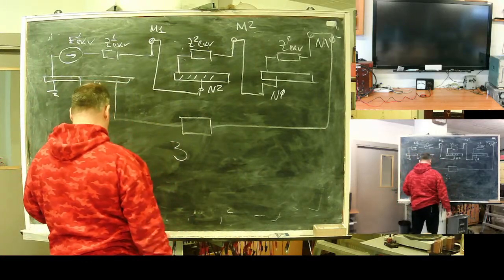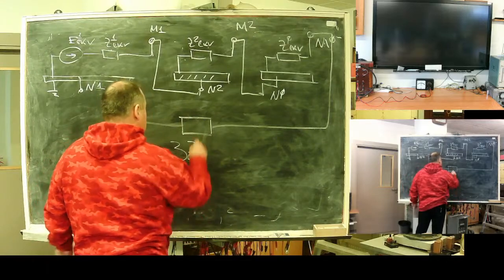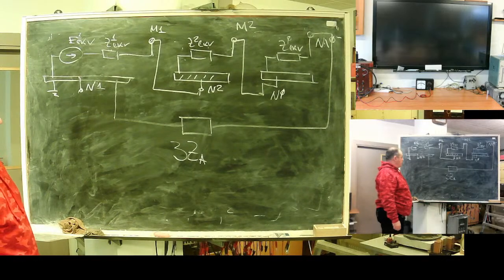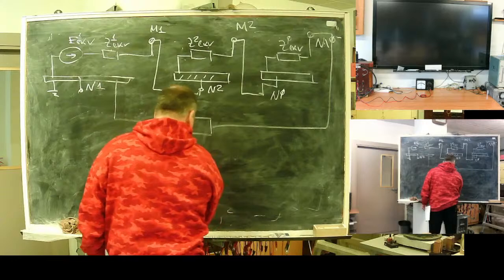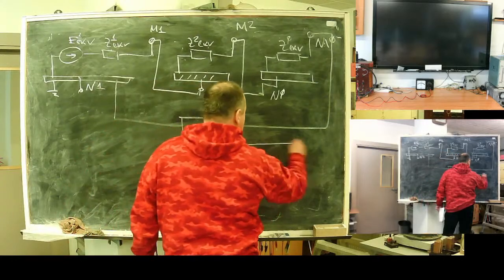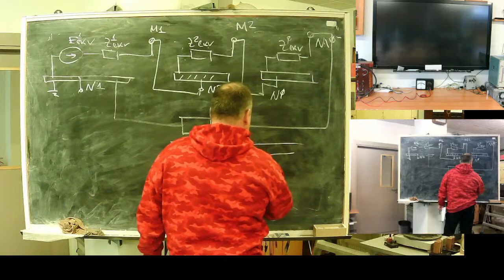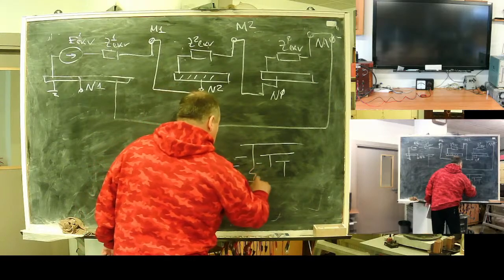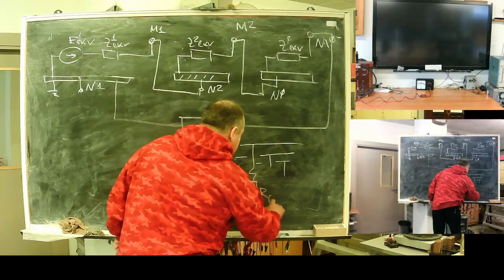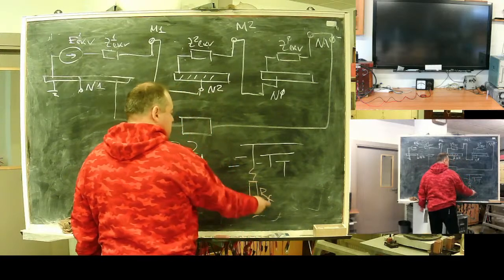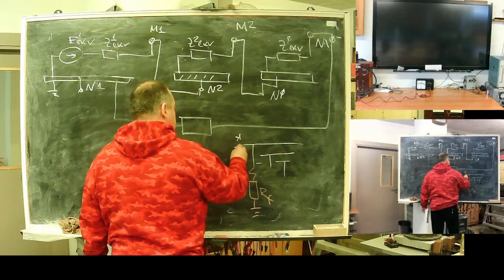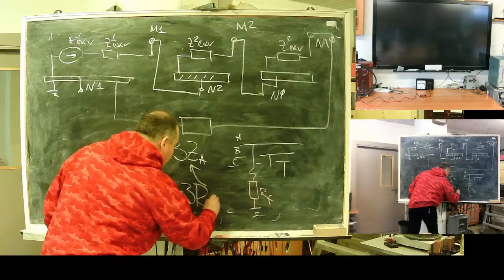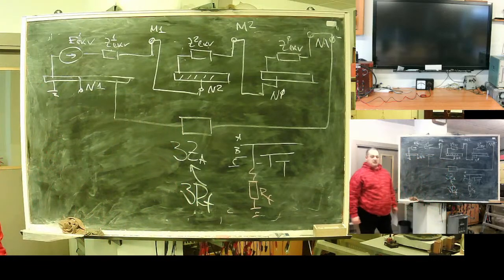triple the resistance at the fault place. In case you have, for example, a three-phase network and an earth fault with transient resistance RF, this one will become triple the fault resistance.